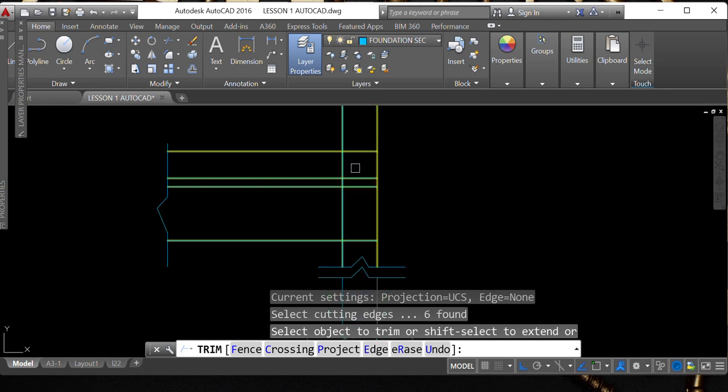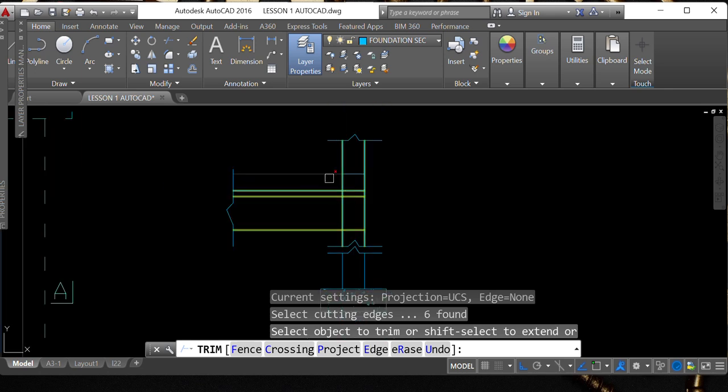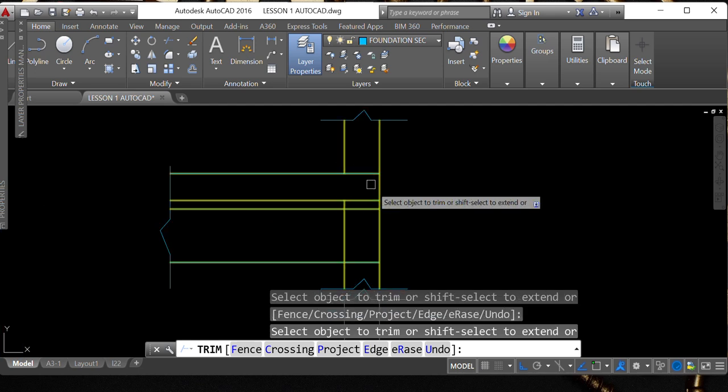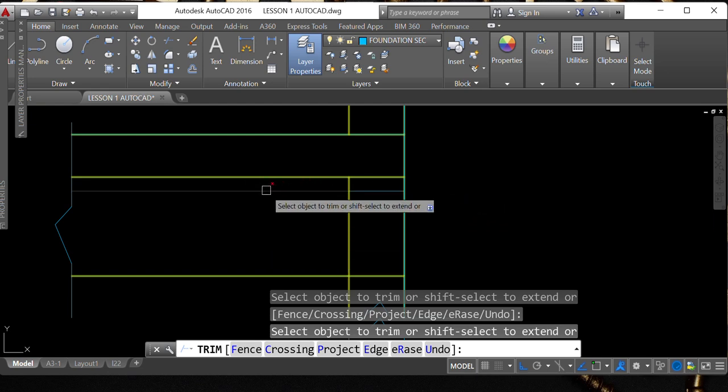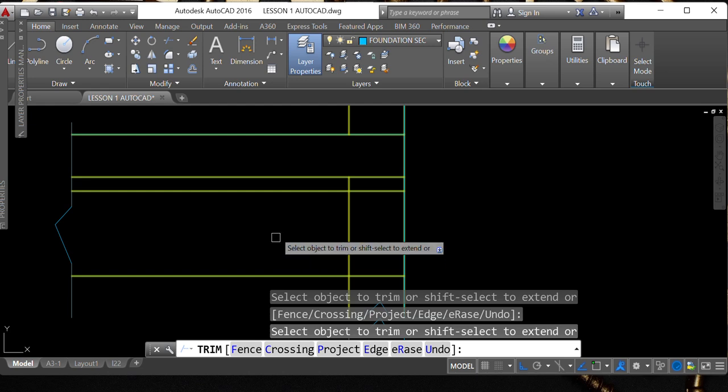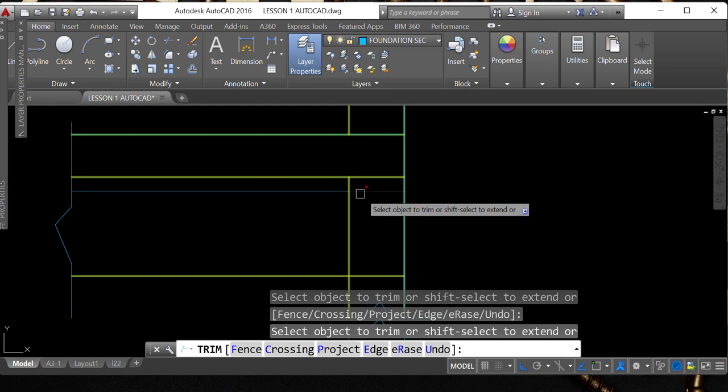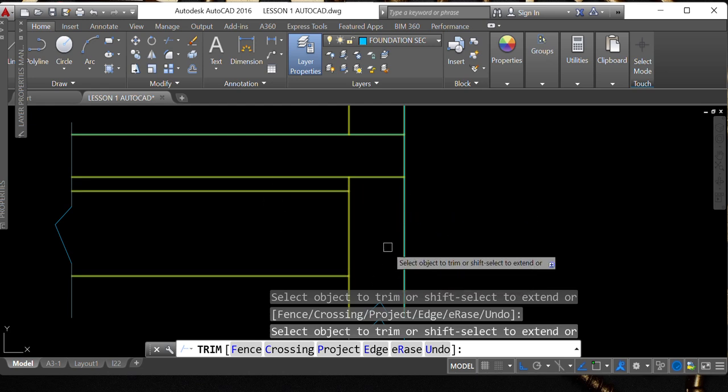There's a break in between. The slab comes in between the substructure wall and the superstructure wall, so you'll have a break here. And then the substructure wall is containing these fill, the backfill, that is the hardcore and the blinding. So I'll trim these.